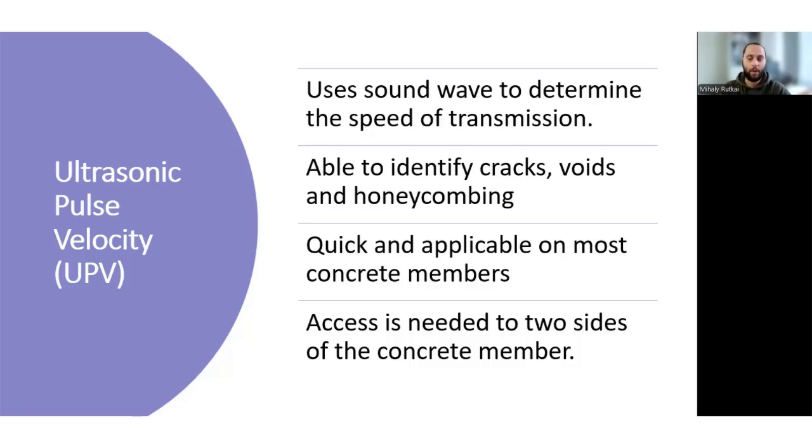So we set up 32 test points around the circumference of a column across 3 slices, spaced 100 millimeters apart. And we found 2 areas where voiding could potentially occur and used comparative signal analysis to determine the quadrant where the defect was located. So with this method, not only were we able to detect a void within this column, but we were also able to guide repair procedures on site straight away by pinpointing the exact location of the voided area so that it could be drilled and subsequently repaired.